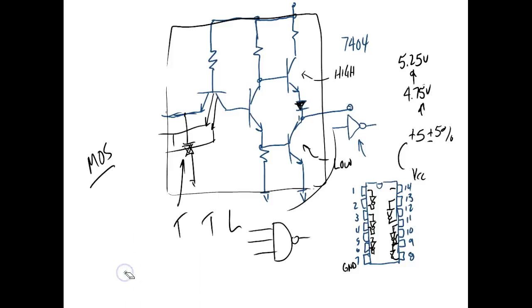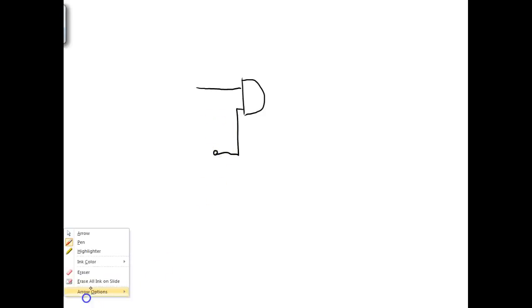So later on, we're going to run into some integrated circuits that have enable inputs on them. So if we disable them, they don't work. If we enable them, they're allowed to work, right? You understand? An AND gate is a very popular circuit to use as an enable circuit. So right now, we'll start off with one input, and then we're going to hook it up to a switch. Let's do it this way.